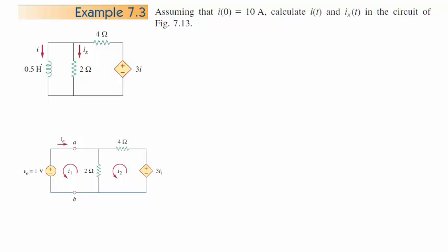If I want to find the Thevenin equivalent right here and here, and I have this dependent source right here that's dependent on the current 3I, the current that's right here, then I have to remove the load. You always have to remove the load. But with a dependent source, you have to put either a current source or a voltage source here, and then, if I put the voltage source here, I find out what the current is in the circuit by normal analysis means. Then I have voltage and current, and I can find an equivalent resistance, or the Thevenin resistance. So let's do the Thevenin approach first. Approach A is Thevenin.